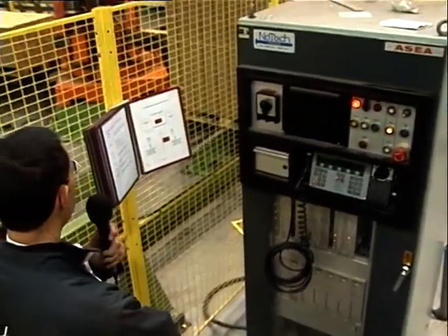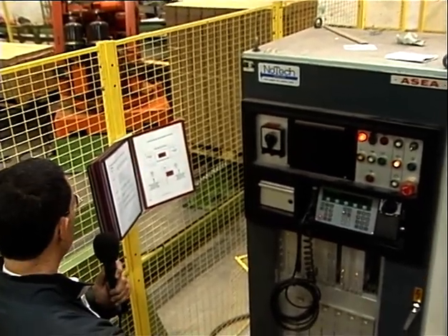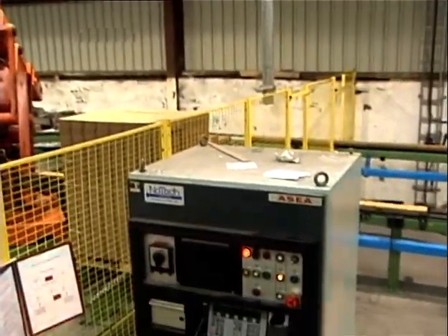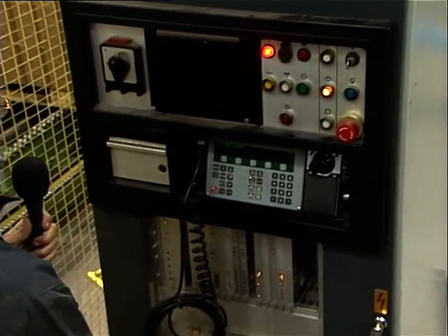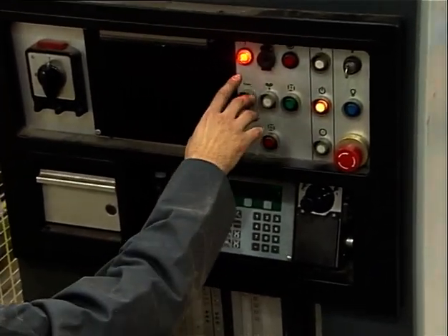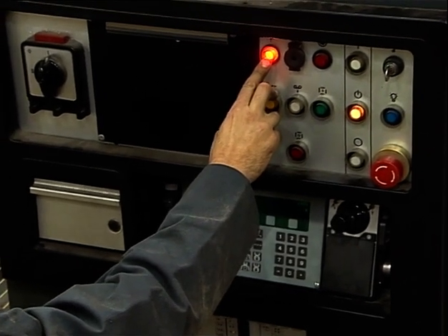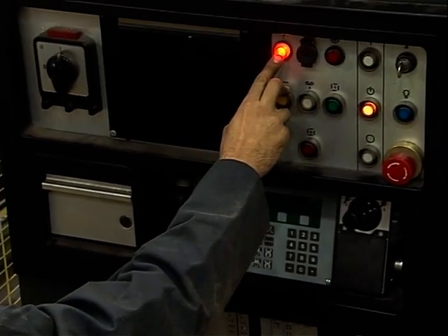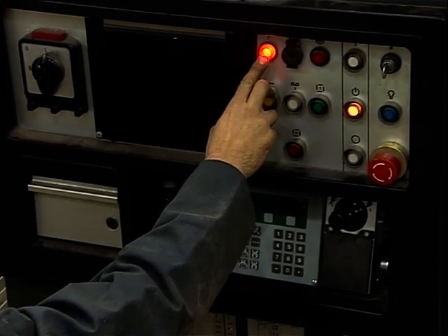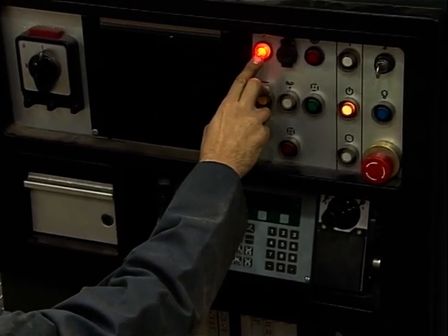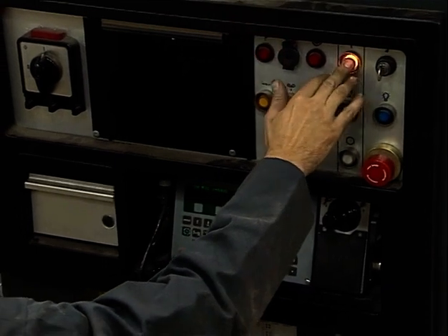Now we have taken away the block on the table, and now we start the robot again in the normal automatic mode. Because Tom has gone through the light beam, we have again emergency stop. At first we take that away by pushing the 1 button.